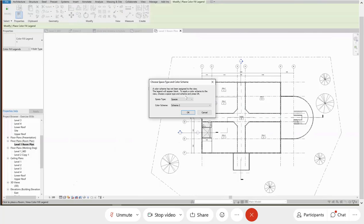After you place the legend, it will ask you what type of color you want to follow. Is it following the space, rooms, or HVAC zone? If you want to go for the aircon mechanical plan. But over here we choose rooms. And the color scheme follows department or name. We follow the name. Then click OK.